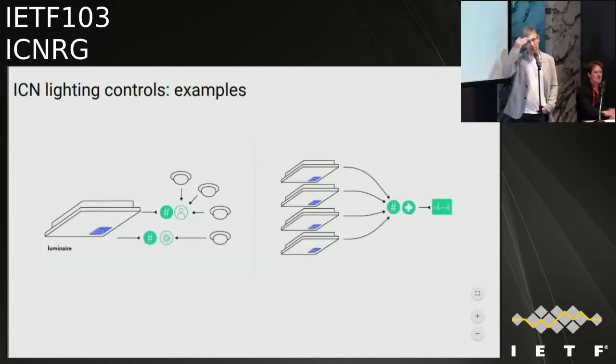And of course, you can have more advanced configuration as illustrated here. So a luminaire may also be interested in subscribing to ambient light level information. That's referred to as daylight harvesting. So the luminaires closer to windows are dimmer, and luminaires that are further out are brighter, to level the light level in the room. So in that case, you need at least two pieces of addressable information. One is the ambient light level, and the other is occupancy. Of course, you might have multiple zones, so that depends on how many light sensing elements you have.